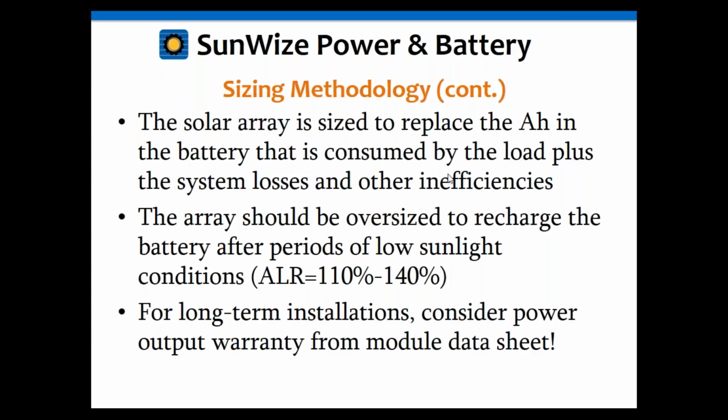Also, along with that, if you're looking at long-term installations, systems that are going to be out there 5, 10, 20 years, also keep in mind, and you may want to factor some of these into the system losses. I'll talk about that more when I get to it, but I know sometimes there are people that will design in the fact that solar modules do degrade over time, up to about 1% per year.